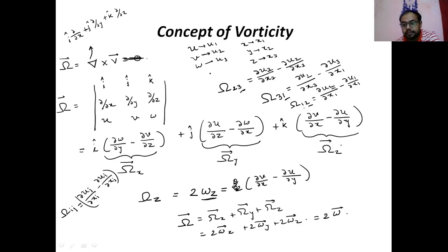So that is the vorticity concept. Now the concept is, if the flow is an irrotational flow, so irrotational flow means del w/del y minus del v/del z is equal to 0, each term will be equal to 0. Each and every factor will be 0. So this term is 0 only for irrotational flow. So the irrotational flow definition is this.